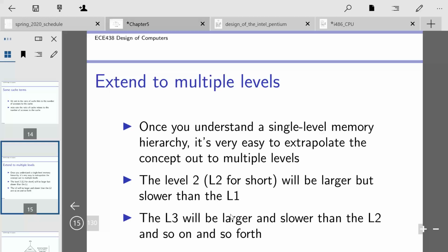And so that's where the unified cache won out over the split cache design in the architects' minds for the 486, because they could fit it on chip. Compared to previous or current RISC designs of that time, those required the split cache because of the five-stage pipeline design that we've talked about quite a bit, where the instruction memory and data memory are separate, and so that meant that those caches had to be off chip because they couldn't fit them all on chip.